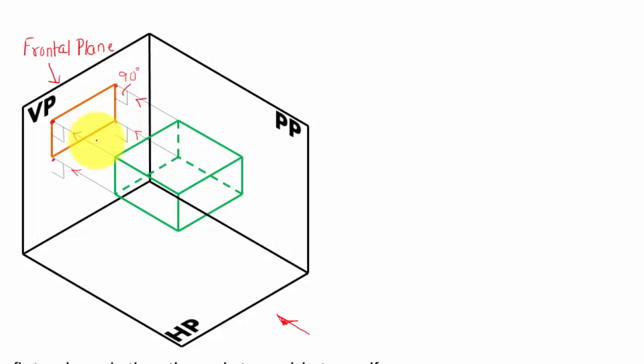So we have this front view, and let's see how the top view can be obtained. For that, we're going to look at this object from the top, and something like this will happen. Let me show you. Again, these are the points at which it has been struck, and you can clearly see when these points are joined in proper sequence, we have a view.